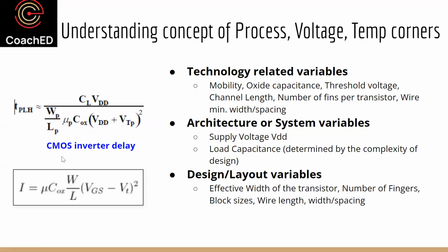So I have to consider these effects and account for them, and study what's going to be the problem or negatives of this, and how I need to margin it or consider it so that my chip still meets my spec. That is the whole concept of PVT, process, voltage, temperature. It is basically an effect of variation or variability in the whole design process.